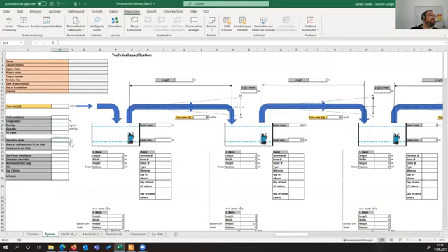especially in this area. What kind of operation do we talk about? Containment or in the fluid, etc. What will actually happen if the pump in the system has been selected incorrectly? This is a very important question. So is the pump too small? It will either be overloaded or the basin can be flooded. If the pump is too big, then cavitation can occur in the piping system, or the pump switches on and off too often and can also be damaged.